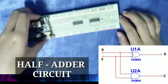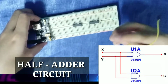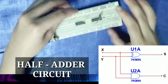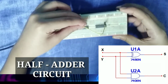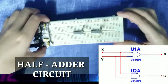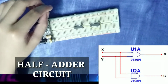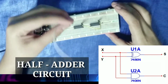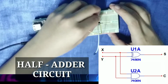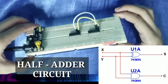And now for our connections, we will be putting our input X to the first pin of our 7486. And as you can see on the diagram, the first input of the 7486 is connected to the first input of our 7408 as well. And for our second input, which is the input Y, we will be connecting it to the second pin of our 7486, and we will also be connecting it to the second pin of the 7408, as you can see here.